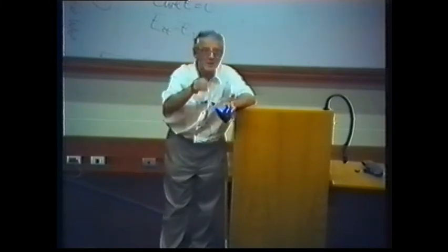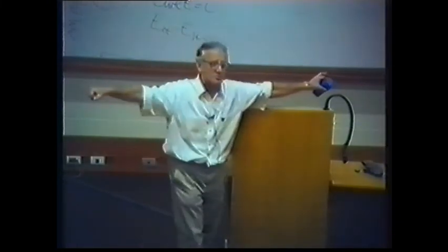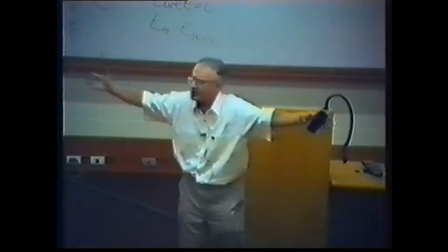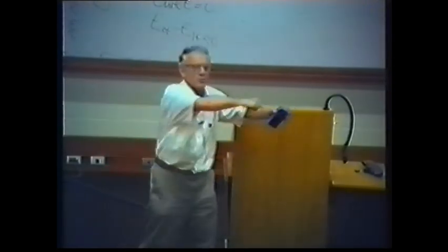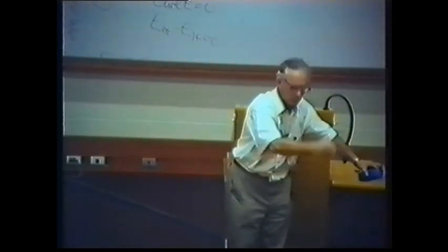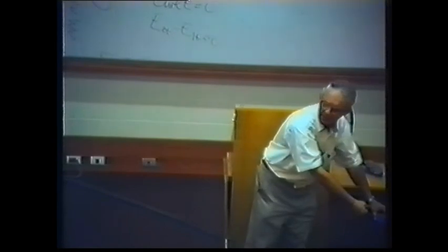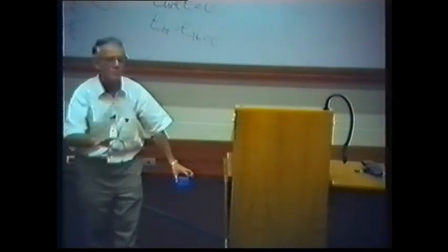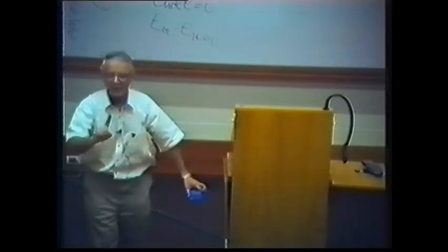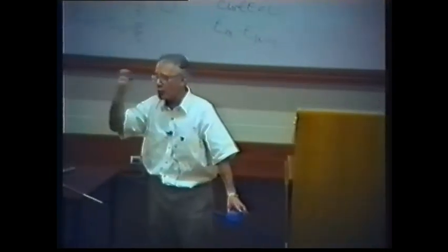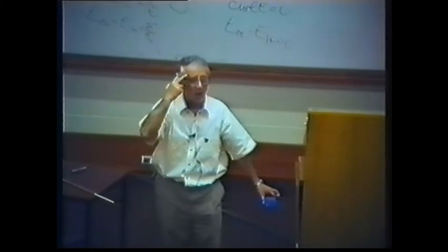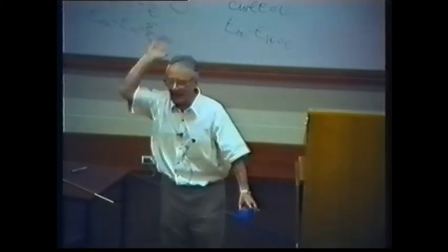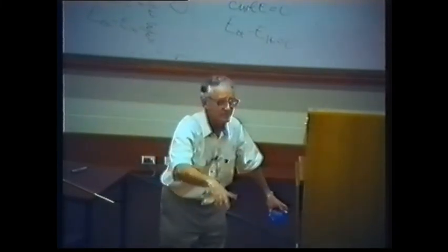You always came to the field, put a short wire, or sometimes long soundings, DC. You put the wire on the ground, connect one point of the wire with electrode M, another with electrode N, and you measure voltage. I don't know one operator who would ask himself how to put this wire. It is laid down on the ground, and that's it.